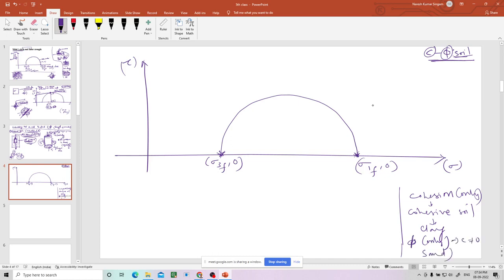Those are generally sands. Sands will not have cohesion; they only have strength due to the friction between the particles. If a soil has both cohesion and friction, those are called C-phi soils. Generally silty soil or silty sand are C-phi soils.